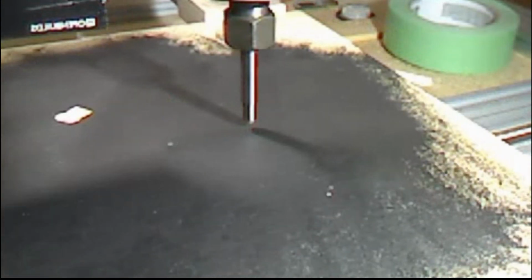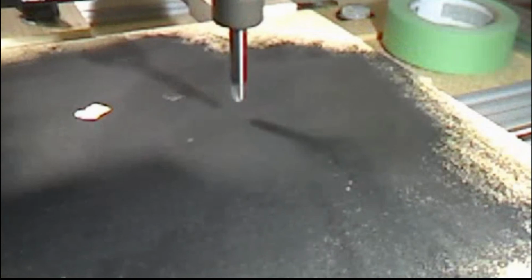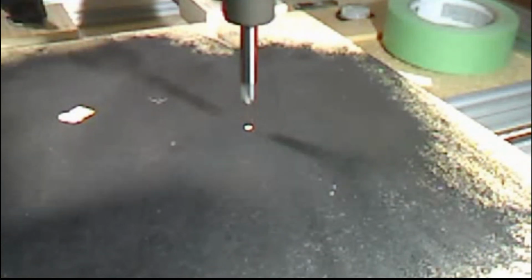What I did now is I moved the 0 over a little bit. And now what I'm going to do is a series of cuts and just slowly lower the head manually until I see it's barely cutting. What I found is this is too big a router and the bit is way too big. So even though I got it to where it barely cuts, because here it was somewhat cutting, but it was still missing. But once I got it to where it was barely cutting, it was still too deep for this.